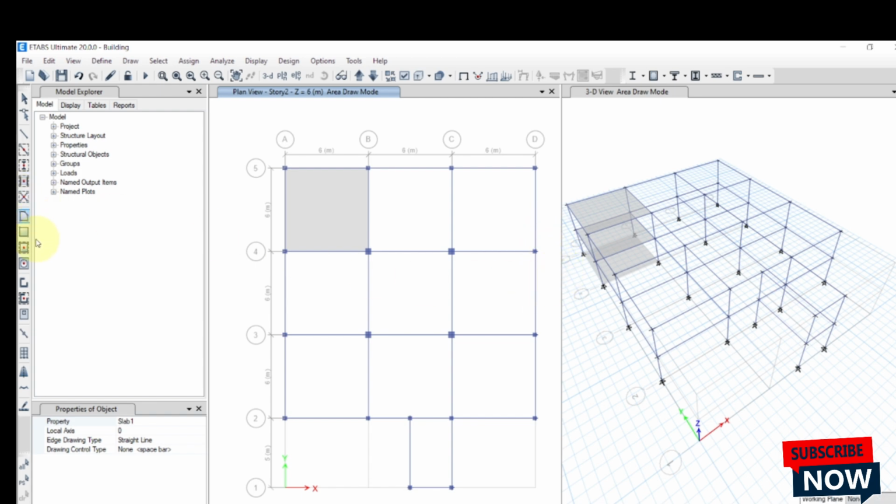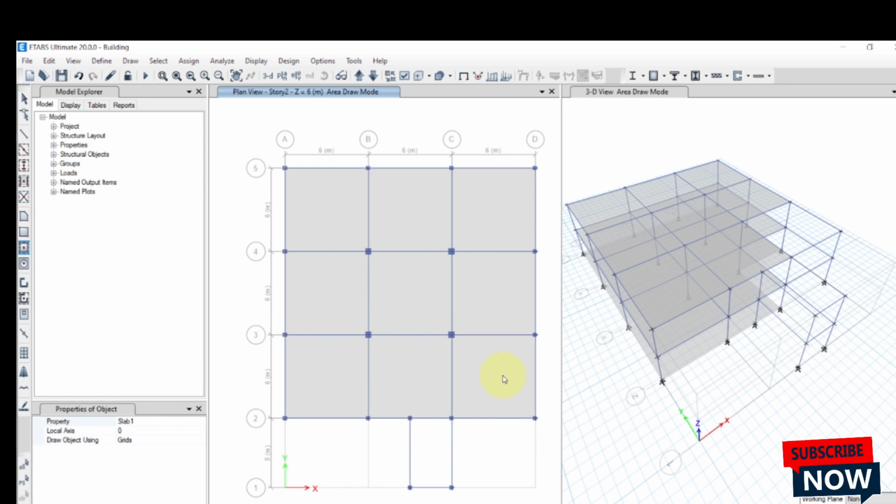But you can also use a different format. We have a quick draw floor, which is much faster. You just have to select the space you want to place your slab. So here, just like that. You just keep on clicking and just replicate wherever you need them. But the problem here is that it's at all stories, so it's even replicating on the base.